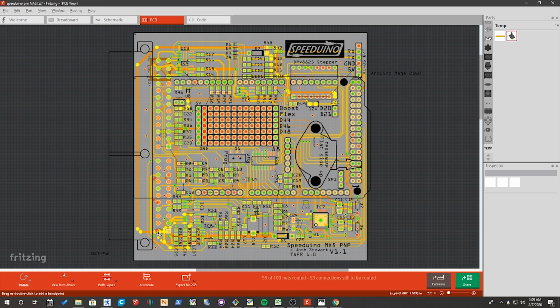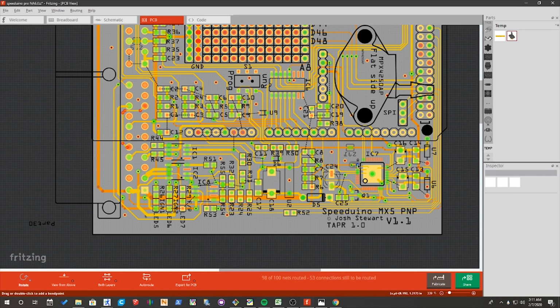So 1B looks like it makes a connection to a little 12 volt pin out, it makes a connection to the DRV stepper up in the top right, it makes a connection to a couple different resistors, and if you look in the bottom right, it actually makes a connection to IC7. And if we move our cursor over to the point on the IC where it was connecting to, we'll see that it's connecting to pin 37 on IC7. So it looks like there's wires that go from pin 1B on our ECU pinout to pin 37 on IC7, and that's our switched 12 volt power.